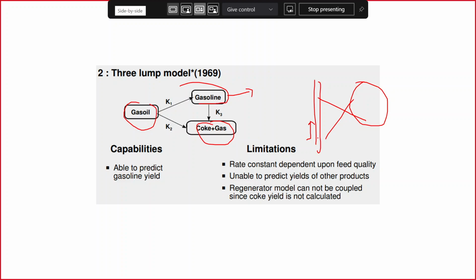The reaction is only in this region, and the catalyst becomes the place for the reactions, because you're cracking it. Remember, you're cracking it. It means you crack the component, and with that, you take the hydrogen out. And then the more severely you do it, the more carbon you produce, which is coke in this case. And then that coke is